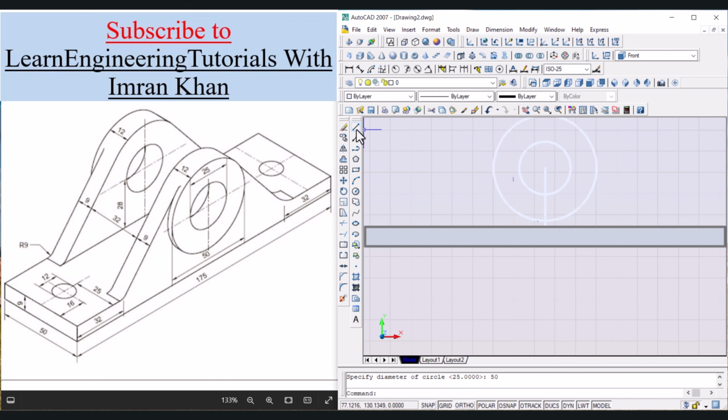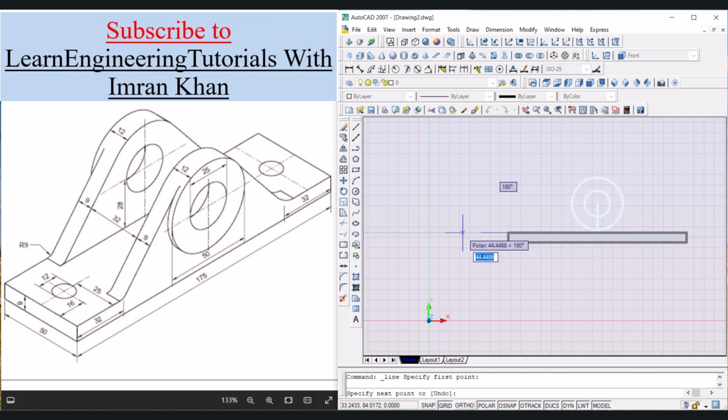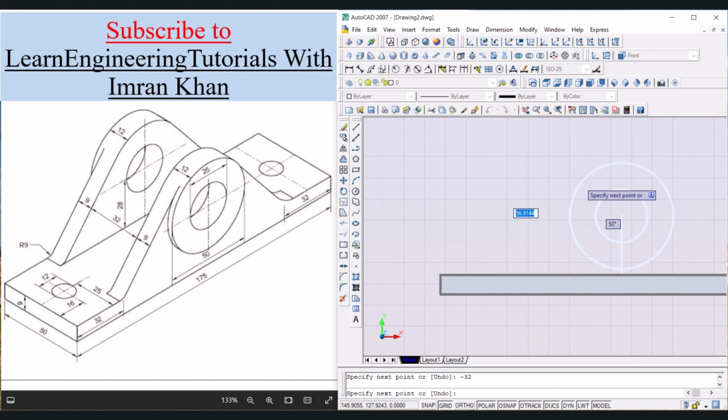enter. Now let us click on this line icon, click on this end point, bring the cursor in the negative direction and write -32, enter. So it has taken that point. Now we have to click on this tangent point, click, press enter.